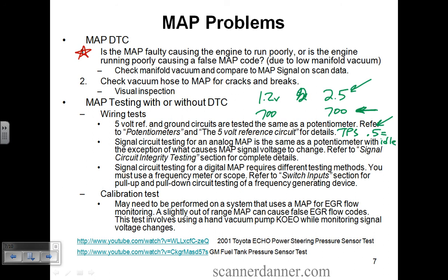What does it get? A MAP trouble code. What's wrong with the car? Oh, you're a rookie. You see a MAP sensor trouble code and you say to yourself, I've got a MAP sensor problem. No, you don't. You've got a bad ignition coil. Waste spark system, 2 cylinders in my scenario. We have to be careful, don't we?